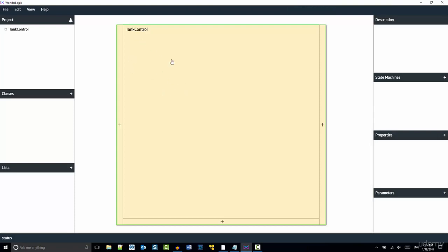Something really simple and a very familiar scenario to us by this point. So here we go. We've got a system that proposes to assumably control the level of a tank. Well, one thing we can start with is, what about if we had some I/O? So I'm going to right click on here and I'm going to add field. And field isn't like in programming when you talk about a form field, something that the operator has to fill out. This is talking about what's going on in the field, outside of the PLC, outside of the machine. That's where all of our I/O lives, right? So we've got inputs coming in from the field on the left, and then we have outputs going out to the field on the right.